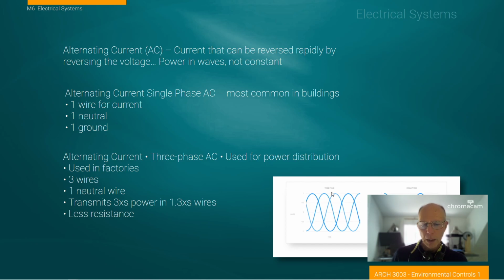The reason three-phase power is popular in commercial applications is that it reduces the sizes of the wires that are required, because it's a more efficient way to deliver electrical energy to create power in motor systems. So most of our home and residential construction deals with single phase power, and a lot of our commercial work will be based on bringing in three-phase power. And once we have three-phase power, we still have the same kinds of availability as for residential single phase, because we can always just tap off one of these phases to get a single phase supply for appliance and or distribution.